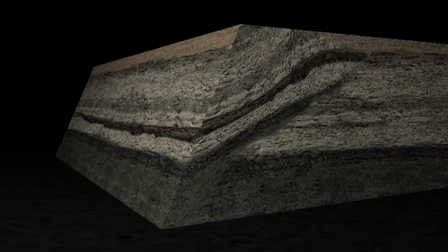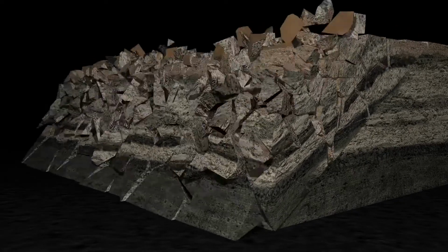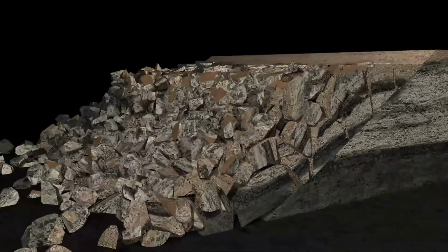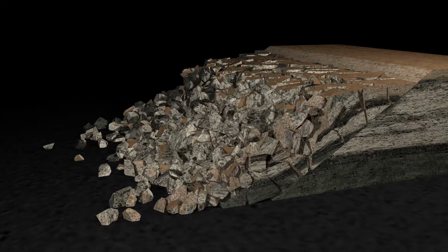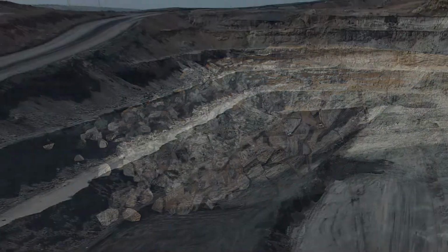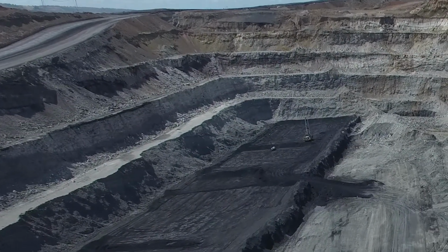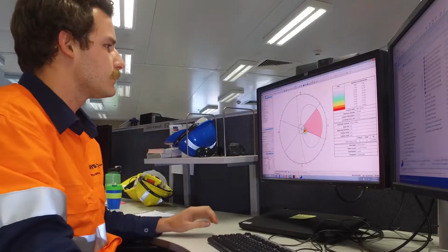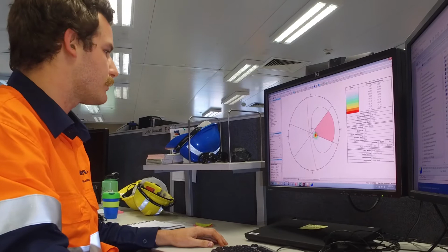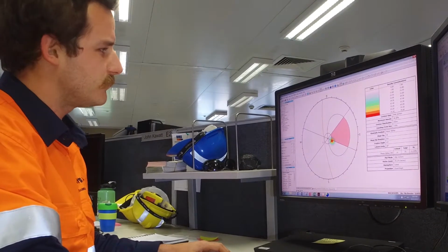By knowing the frequency, orientation and location of structure in advance, modifications to strip geometry can be made to engineer out potential stability issues that are structurally controlled. Provisions to actively manage failing material, such as incorporating appropriate bench widths, can also be built into the design. Recommendations and requirements for blasting can be made if this type of structural information is available.